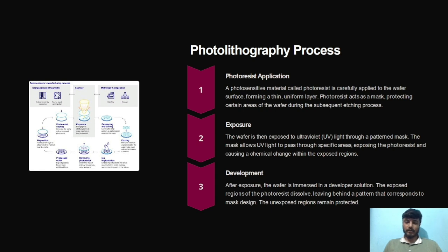Exposure. The wafer is then exposed to UV light through a patterned mask. The mask allows the UV light to pass through specific areas, exposing the photoresist and causing a chemical change within the exposed regions. Development.